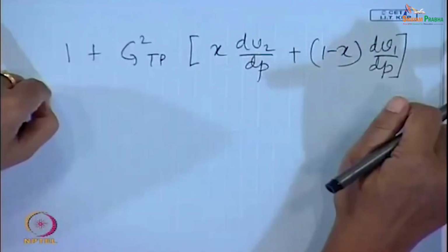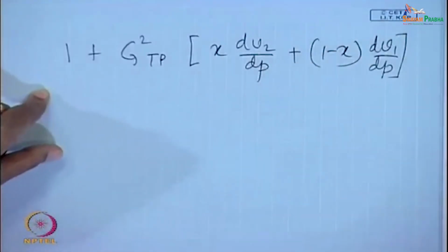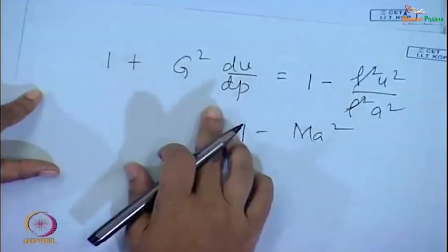But the same approach was used. We have used the continuity equation, we have used the momentum equation, and we have considered the acceleration pressure drop due to the density changes of the fluid. Usually one fluid is compressible, the other is not, but to keep matters generalized, we have considered compressibility of both the phases. Finally, we have arrived at a denominator which is of the same form that we had obtained for the compressible fluid flow cases.